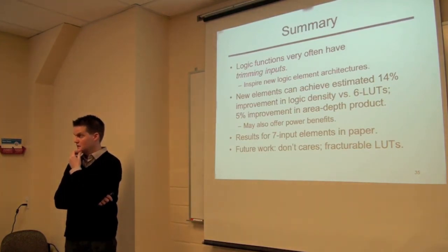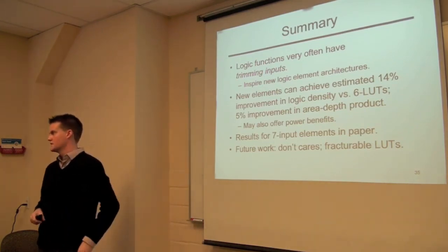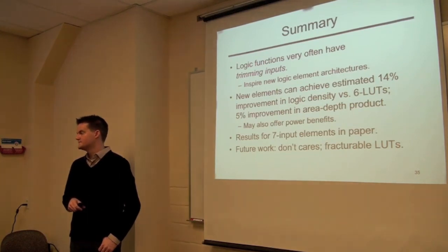You need a different delay for every LUT input. I didn't participate in the 5.0 upgrades, but the older version of VPR could do that in the timing graph, just not in the architecture description. Once you upgrade that timing, you at least get the LUT impact. You would probably still have a somewhat optimistic answer, because you're modeling a little more routing flexibility than commercially built nowadays. But you can just say it is what it is, you model this with that answer.